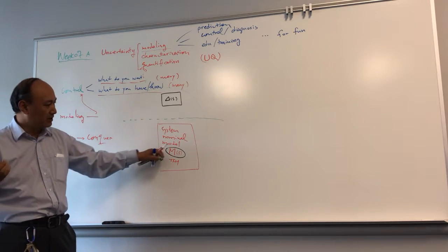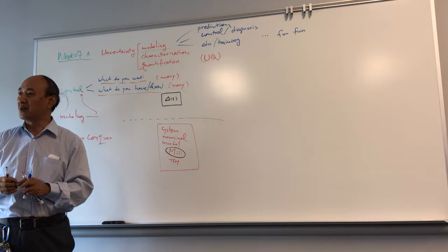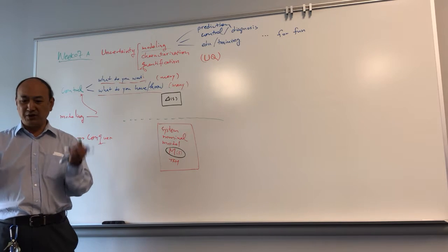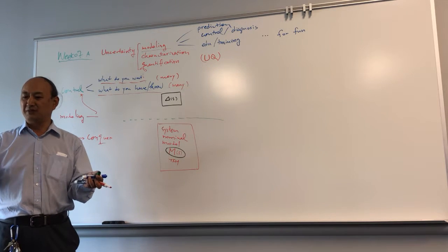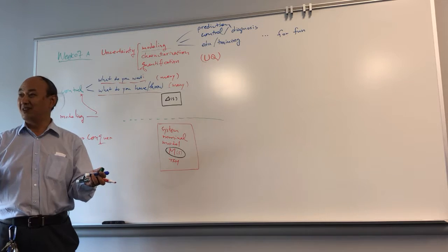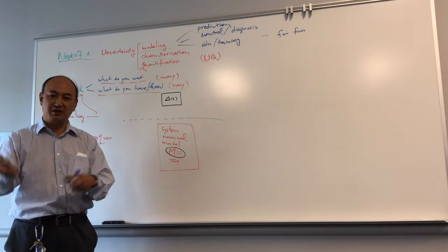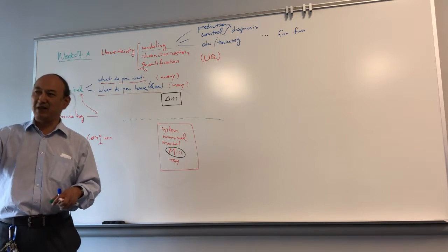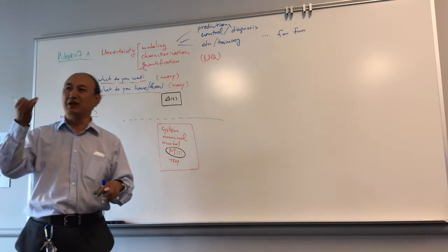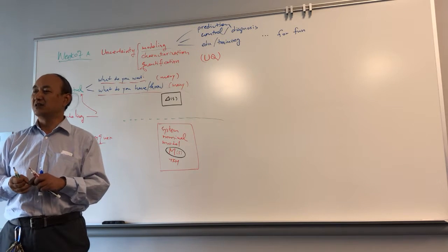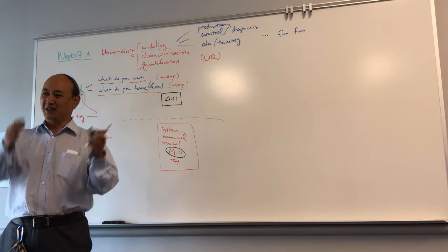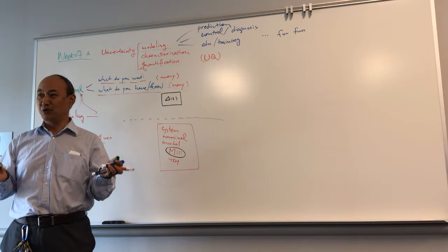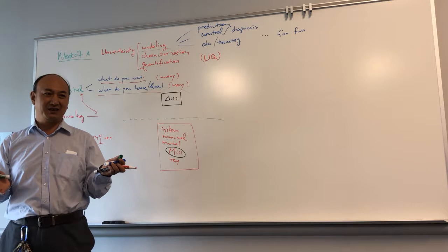We talked about even coprime factorization format, and so on and so forth. And in between, we talked about the conversion between them. One of them is called realization, giving this one how to realize the state space. In the space, we talk about minimal realization, we talk about balanced realization, and by the way, we also discussed Hankel singular values. Then rank them, we truncate the tail, and we can easily do model reduction, right?